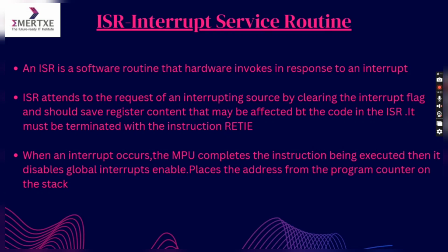ISR, Interrupt Service Routine, is a special kind of software routine that is automatically executed by the microcontroller in response to a specific interrupt. An interrupt is a signal that temporarily halts the main program and allows the microcontroller to execute a different task. When an interrupt occurs, the microcontroller completes the instruction it is currently executing and then disables global interrupt.